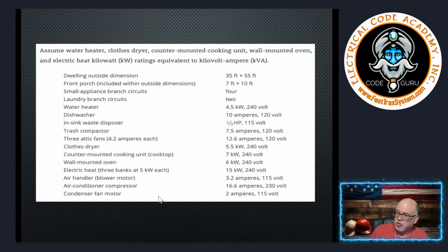All right? So it's only the 240 volt loads, except for the range and the dryer, which obviously you electricians are familiar with, right? We're going to run 4 conductors to those, and they have some elements in there that are going to need 120 volts. So definitely we're going to have some neutral loads associated with the dryers and the ranges. So we will take care of that as we move through it. But just so you know up front, they're going to be at 70%. And we get that allowance in 220.61(B). So anyway, we'll work through those type of things.